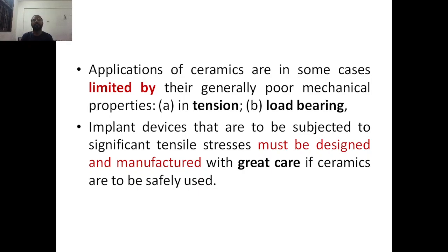Applications of ceramics are in some cases limited by generally poor mechanical properties. For example, they cannot bear a lot of tension or a lot of load. These two are the major drawbacks of ceramics. So implant devices that are to be subjected to significant tensile stresses must be designed and manufactured with great care if ceramics are to be safely used.